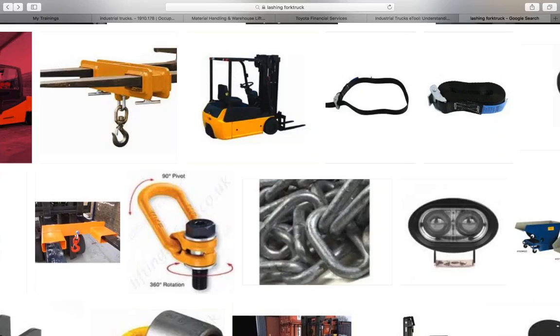All right, let's talk about personal safety of riggers and hoisting operators. Let's talk about some common sense rules and safety practices we should observe. First of all, look at number 1. What's number 1? Always read the manufacturer specs, those manufacturer's instructions, and whatever they tell us, we do. We do all our pre-operation checks, we follow the guidelines, we do our periodic inspections, and ultimately we make sure that we have the information available for the operator, right?